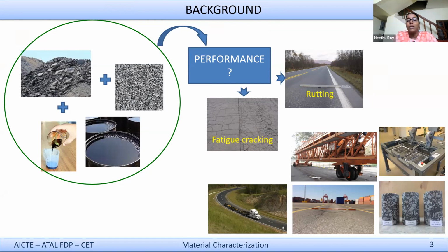Now, if it's not possible, you do some test stretch studies, right? You are aware of it, I'm sure. See, this is an NCAT test track, wherein you construct the test track, the actual pavement structure, with the kind of materials you want to explore, with the kind of thicknesses, with the kind of layers and all, and you will load it with a known load quantity and known load factor, which will be continued for a couple of years or a couple of months, and you collect all the possible information regarding how this pavement is performing. Now, even if this is not possible, you go to an accelerated loading facility.